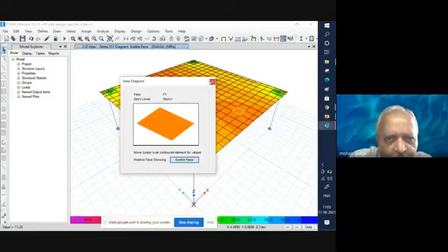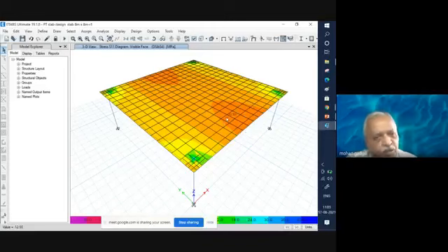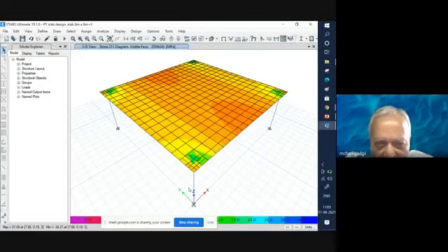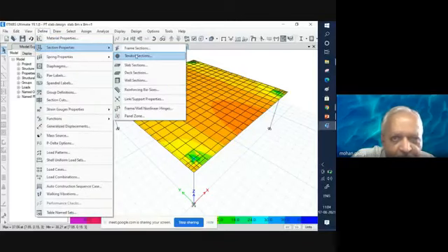So you can see that for different loading cases, you will be able to see the stresses at different points. For all these elements, you are able to get the stresses and so on. So this will be a very simple task for you. You generate the model by using simple commands of ETABS software. For that, you need to define the material, you define the sections for slab or beam, you define the support conditions, then you define the reinforcement that you are going to use, consider the loads, and for prestressed concrete, there is only one change, and that is you are going to use the strands. So for that purpose, you need to define the section properties in strand.